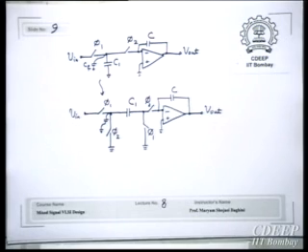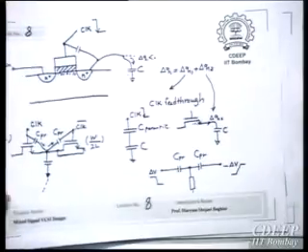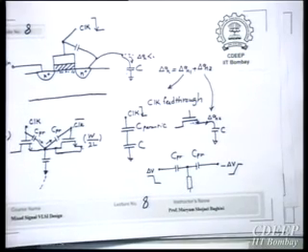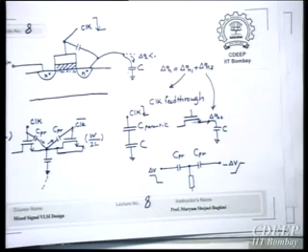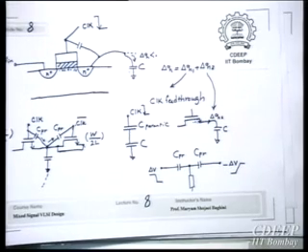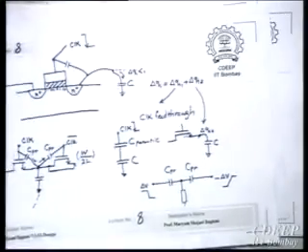Yes, clock and clock bar should be almost synchronized. Nobody says that it is an ideal solution. Nobody can say that there won't be any leak here, for example, that this will be perfect and clock bar will have exactly the same edge. But it is possible, with a good clock generator, to adjust the delay. For example, how do you design a clock and clock bar which are synchronized?